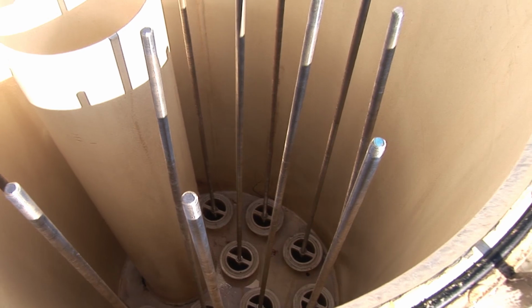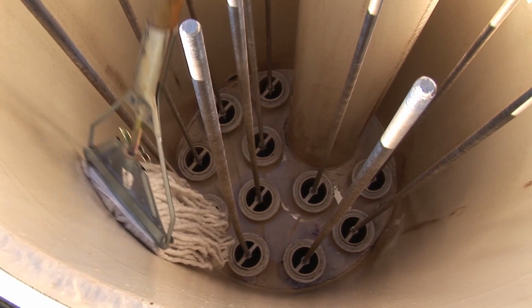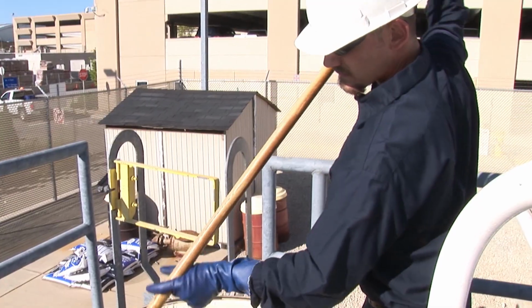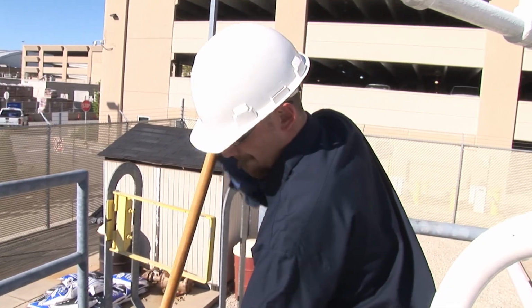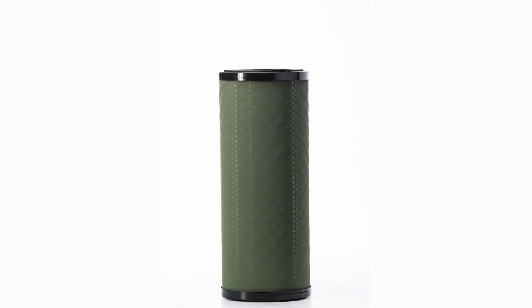Check the housings, epoxy lining, and repair any damaged areas with an approved repair kit. Remove the inlet chamber, clean out, cover, and wipe the area inside until clean. Clean all hardware before you reinstall the elements. Some housings will contain synthetic or Teflon separator cartridges. Both types need to be cleaned and reinstalled.